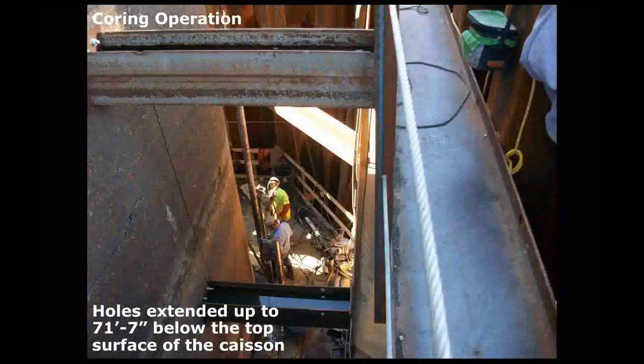And here's a photo of that coring operation. The holes extended up to 71 feet 7 inches below the top of the caisson when we were drilling these in. And that was based on the tension results from our analysis. And this coring operation led to our second surprise during construction, which is that we expected these caissons to be solid concrete. We found there was a lot of material embedded in them. There were wood timbers and there were steel form supports that we hit as we cored down, and which greatly slowed the progress of the coring.